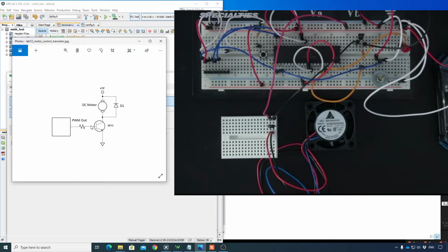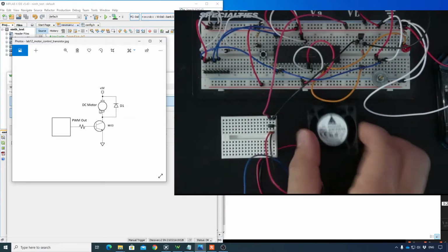Okay. So let me just talk about what's happening in here. The pulse width modulation, if you guys remember, is just basically as if I'm applying some voltage between 0 all the way to, let's say, 5 volts. It's just turning on and off that particular transistor, and pretty much you're controlling the DC motor. I'm controlling how much voltage it has on it. So let me just show you how it actually operates.